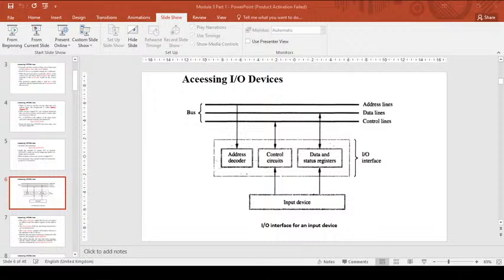Okay, so that example illustrates program controlled IO in which the processor repeatedly checks a status flag to achieve the required synchronization between the processor and an input or output device. So continuously checking the SIN and SOUT flags, or continuously monitoring the SIN and SOUT flag registers for reading the input device and displaying onto the output device, is also called polling. Continuously monitoring something is called polling. So we say that the processor polls the device.